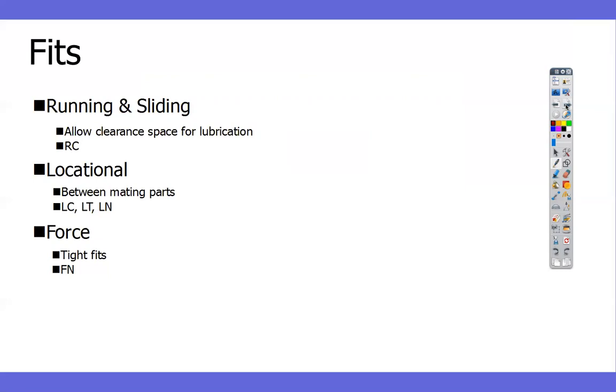I did this earlier. I had this little smart switch that I got from a friend, and he didn't include a housing for it, so I made a housing. I drew it up, and the main part of the switch fit through fine, but the first one I printed didn't fit together. This part went in fine, but this right here had to go into a little slot, and it didn't fit because of how the 3D printer made it a little too big. I didn't take into account the fit based on the 3D printer. I thought I had, and I didn't use the right number. So I had to reprint it with a better fit, and now it slides in there perfectly.